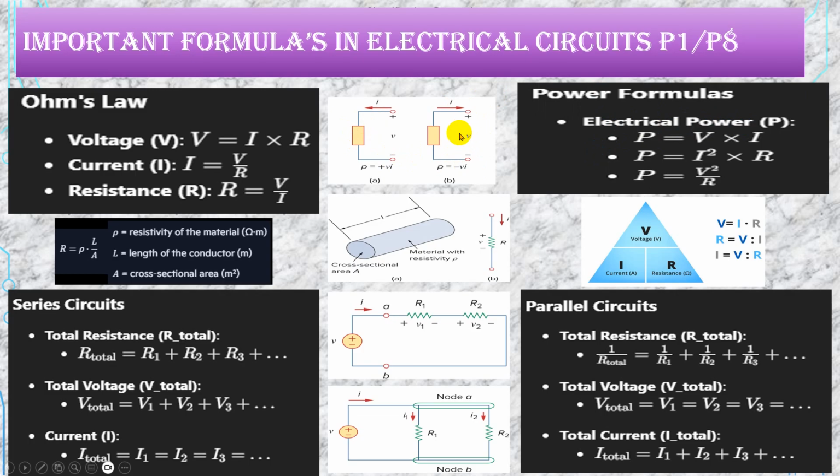So electrical power in terms of Ohm's law we can also include here. P is equal to VI is the general equation. Now substitute V in terms of I and R. V in terms of I and R is nothing but V is equal to IR. Substituting IR for V, I multiplied by I gives I square R. Now for another equation for V into I, we substitute for I. I is nothing but V by R. So substitute I is equal to V by R. So V into V gives V square by R. This is your power.